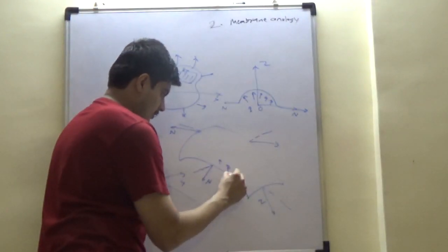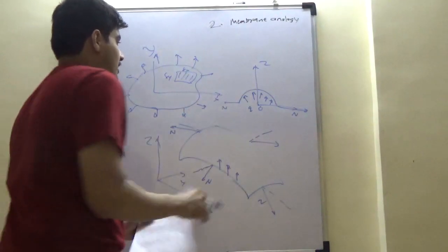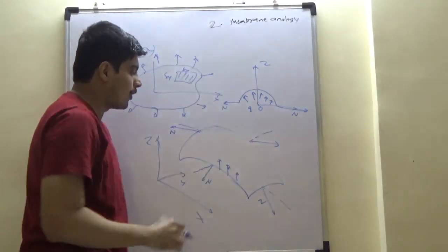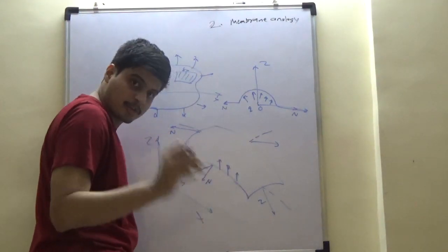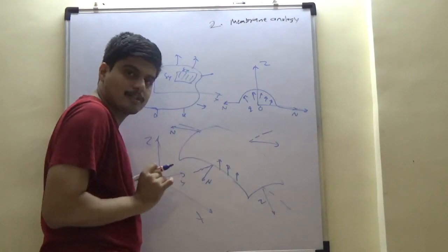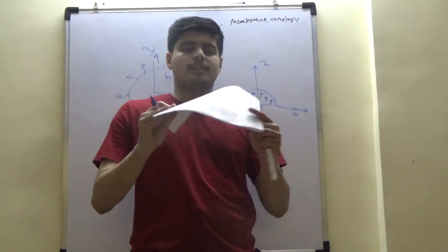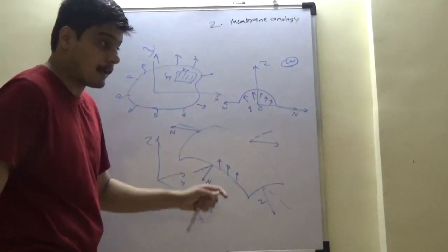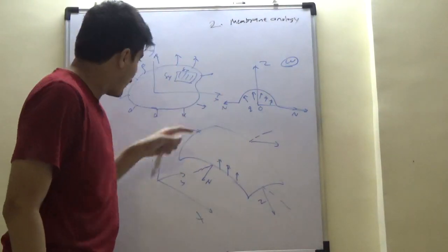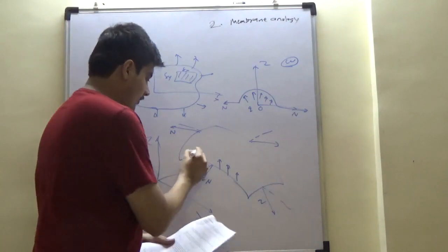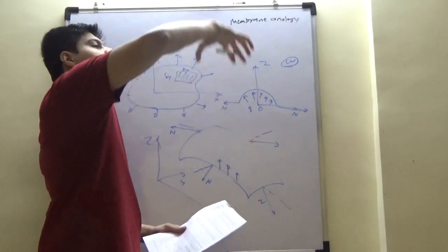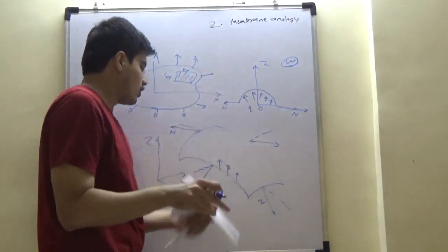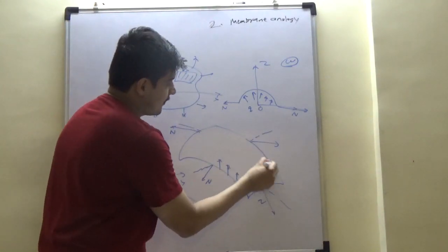And this is such that n has to offset the projection of the component of this cube, so that the load Q, which is a per unit area uniformly distributed load, is offset and balanced by this. Now, in the membrane analogy, the vertical displacement in Z is W. We don't know whether it is warping, but it is simply the elongation in the third direction to enable resisting of this load. But we know that this Z, the bulge in the Z direction, is going to be a function of xy. It may not always be uniform and constant.